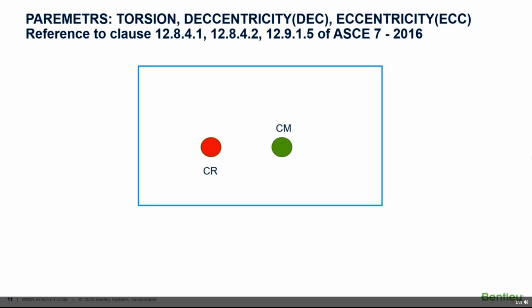Finally, we'll discuss the seismic parameters that have been talked about in detail in our ELFP session, or the equivalent lateral force procedure session. But here, this pertains to the response spectrum specification. SS and S1 indicate the mapped acceleration parameters that we have discussed a couple of slides back, while the lat and long mean the latitude and longitude from which the MCER parameters can be retrieved from the maps in Chapter 22. ZIP also indicates the location from which the SS and S1 parameters can be identified from the maps.